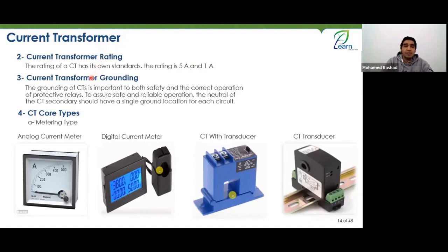The other parts. Okay, let's move on to current transformer grounding. Usually, we see that the secondary side of the current transformer is connected in a star or delta configuration as a 3-phase to feed into the measuring device or our load device, reading 3 currents or 3 connections on 3 phases, red, yellow, blue. And the star point is grounded, right?